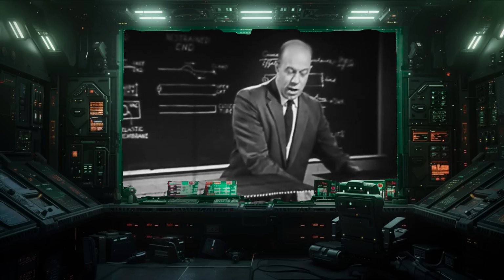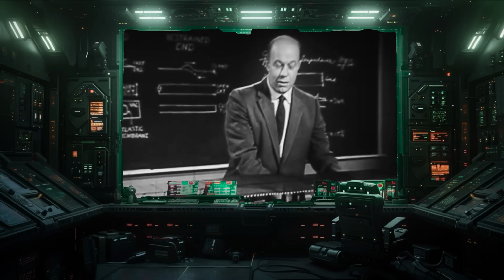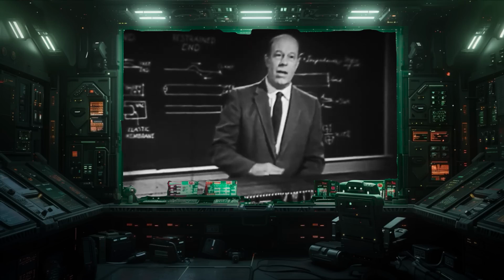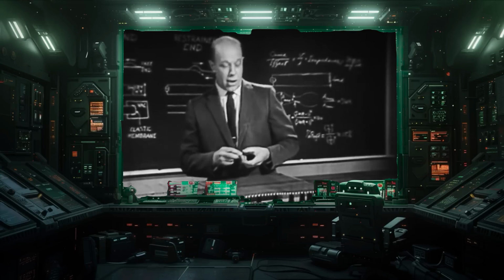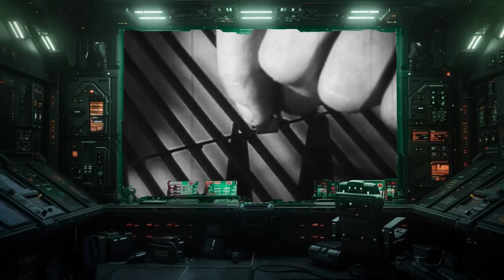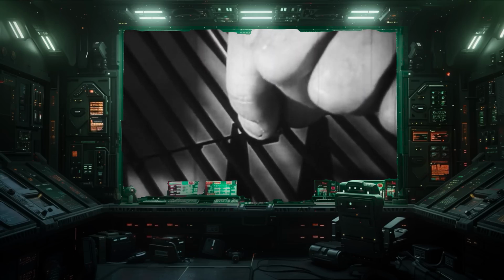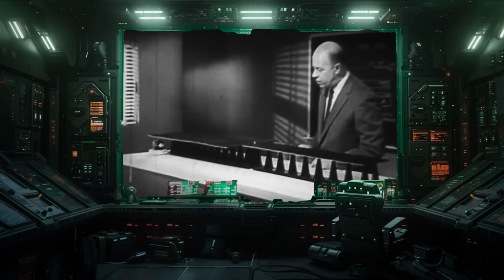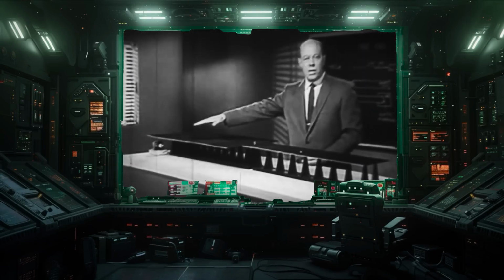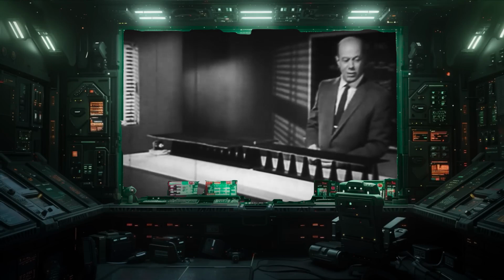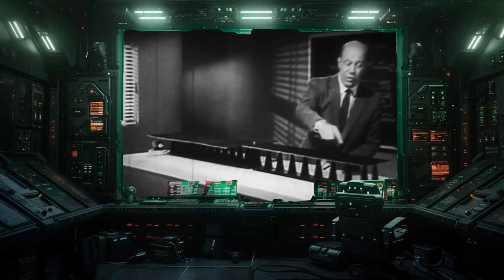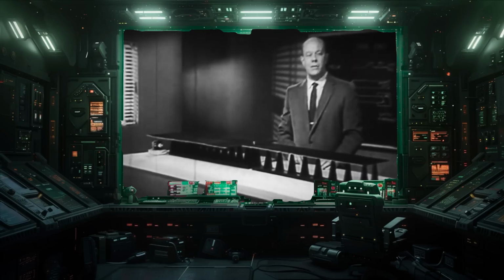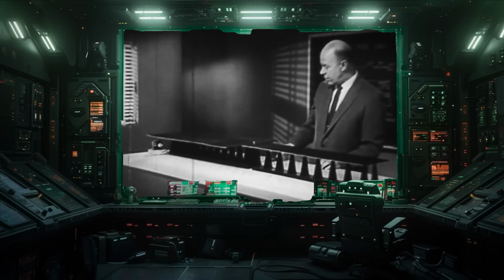Suppose I connect these two wave machines end to end. Together they give me a single transmission line made up of two pieces having different impedances. At this point, where the two central wires are clamped together with this little clamp, there is an abrupt discontinuity in the impedance of the transmission path. A wave traveling slow along this medium will suddenly speed up when it crosses over into this one. This behavior is similar to what happens to a beam of light when it emerges from glass into air.